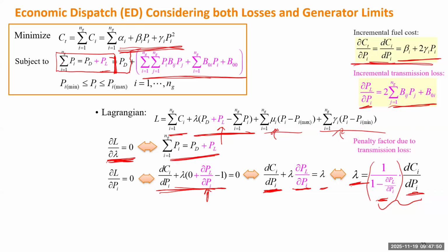But if we look at that cost from different points of the network, such costs are different, because they need to consider how the transmission loss can influence that cost. So when the transmission loss is zero, meaning it doesn't change with the power output, this entire factor becomes 1. So that goes back to the original case when we ignore transmission loss.